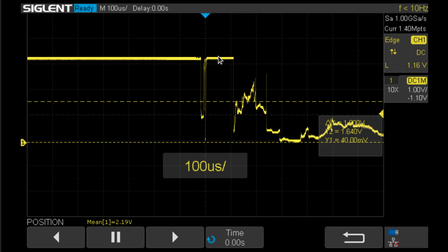It would be operating as a low-pass filter, and the debouncer that's symmetric and waits until it's stable before it changes the output of the debouncer would eliminate this, okay? So it really depends on the noise in your system, depends on how long you're willing to tolerate waiting for the synchronizer, or rather the debouncer, to decide that it has been stable long enough to propagate it through and so on, all right?